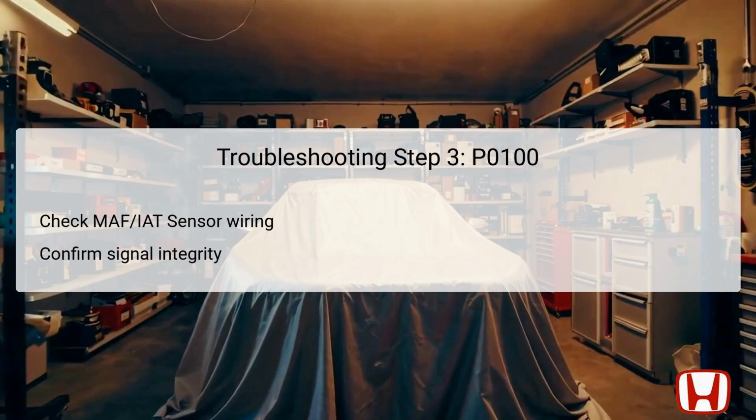Should the issues persist even after replacing the sensor, the focus should shift back to the PCM for further inspection. Accurate diagnosis in this step is crucial, as it directly impacts engine performance and emissions.